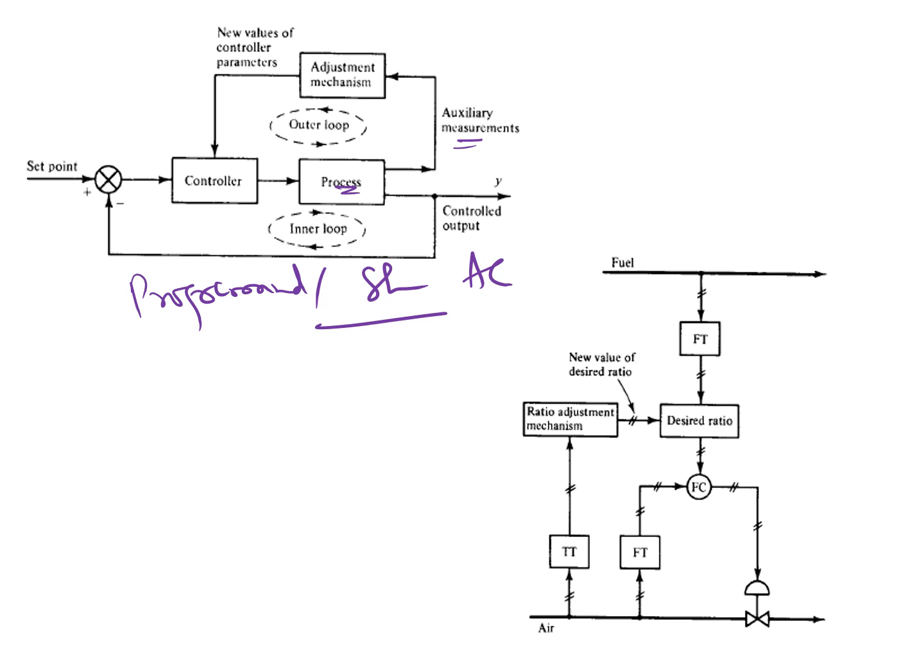Let me explain this with one example. This is a normal ratio controller. How it works: this is FA, and as we already discussed for the ratio, this FA into 3 by 2 should be equivalent to this one. So you have to change the controller until this flow rate is equivalent to this. Say, for example, this process is non-stationary, so you will not be able to achieve this FA into 3 by 2 because of the non-stationary or non-linear process.